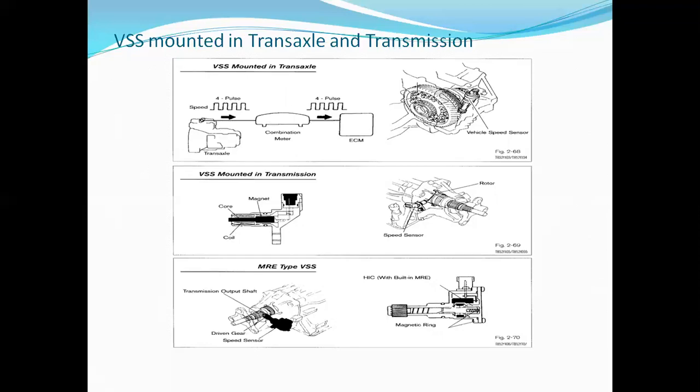So depending upon the acceleration process, simultaneously the camshaft timing chain needs to be changed by the programming given by this particular processor, and that processor will be guided from the controller. So depending upon the feedback from this particular sensor, simultaneously the actions or guidance will be given to the processor from the controller to increase the speed or decrease the speed.